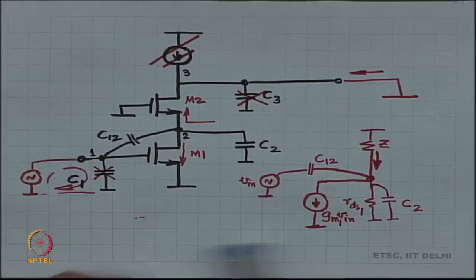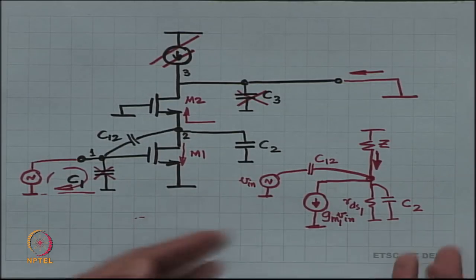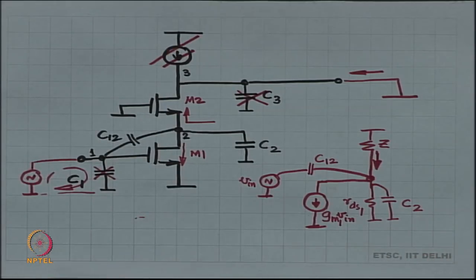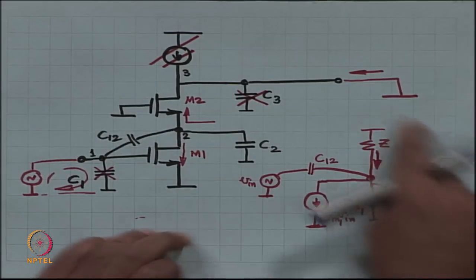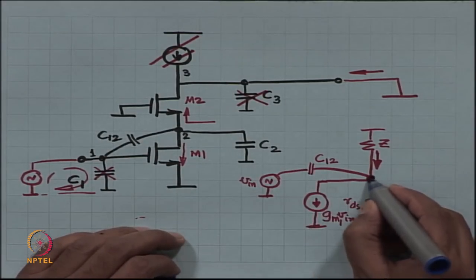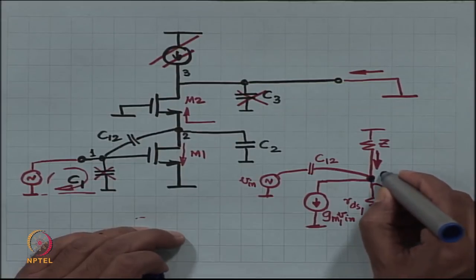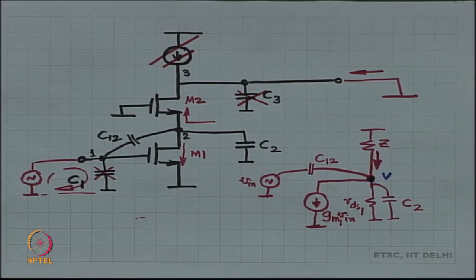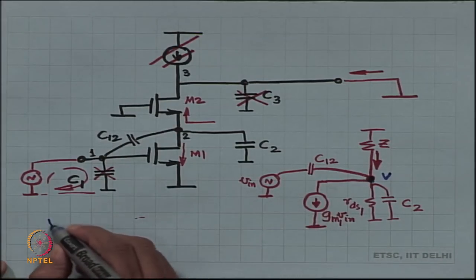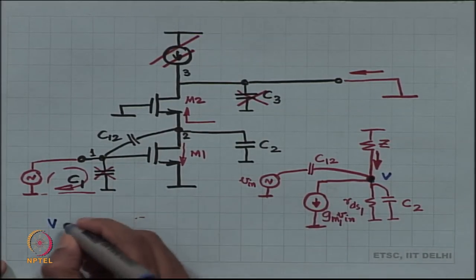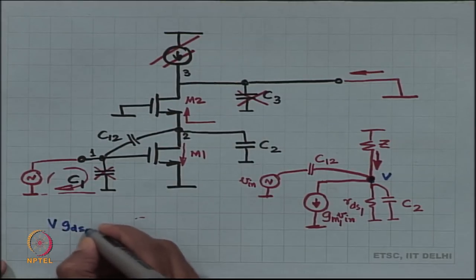Another possibility is to just do a short KCL. Okay. In this particular case, the short KCL is going to work to your advantage, right. It might work out faster. So, you look at this circuit, you say that I do not know this voltage, let us say this voltage is V.